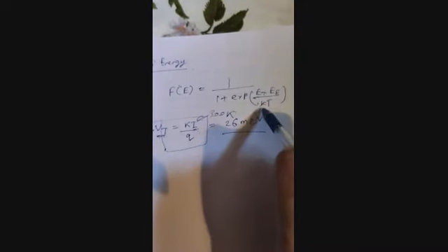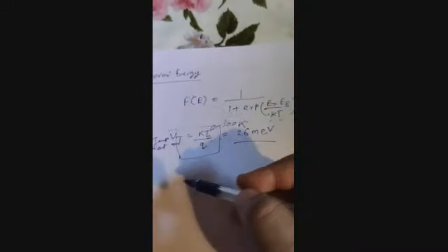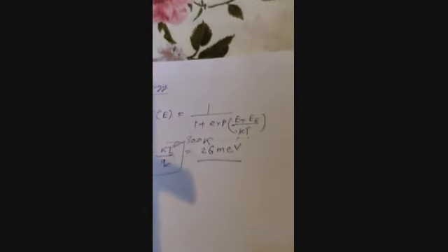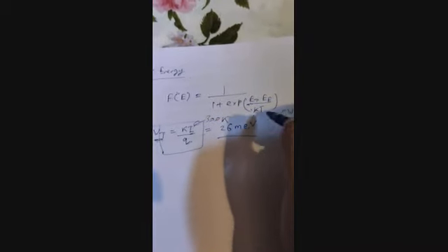So what I have done here is divide the energy by kT by Q, normalizing the energy with respect to kT by Q. Energy of an electron is generally shown in electron volt, and kT by Q is also in electron volt. So we are basically normalizing the difference E minus EF with respect to kT. So kT is the smallest quantity for consideration.